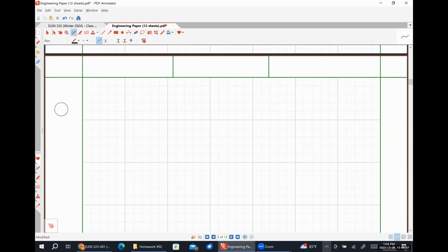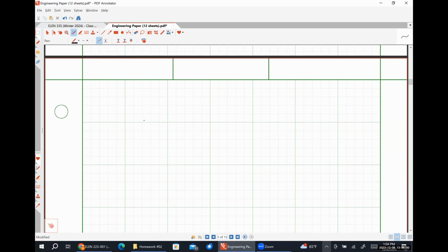So I'm going to start with my practical op-amp model. So here's V minus. And then I have my infinitely large input resistance. Here's V plus. This is my differential voltage, VD. Over here, I have infinity times VD.